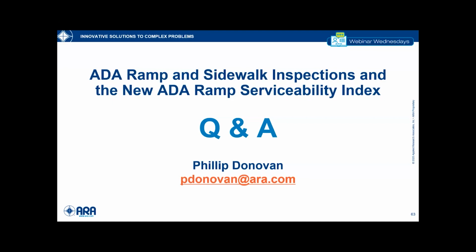Thank you, Phil. Aaron wants to know, when is ProWag going to be officially adopted? Do you currently consider something ADA compliant if it meets the 2010 federal specifications? Great question. ProWag was implemented by the Department of Transportation on January 17th of this year. The Department of Justice has not adopted it, and there is no schedule for adoption by the DOJ.